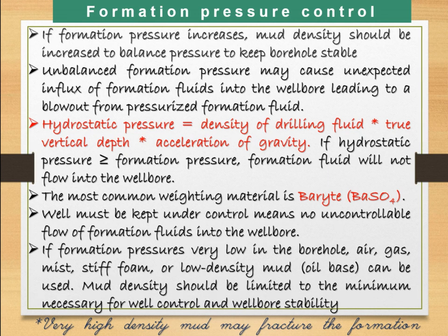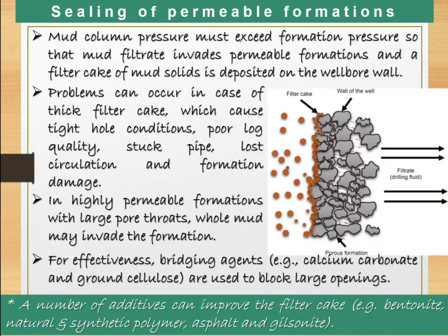So in those cases, air, gas, mist, stiff foam, or low density mud, often oil based, can be used. Mud density should be limited to the minimum necessary for well control and wellbore stability. Very high density mud may create fractures in the formation, so eventually we will not get proper recovery.